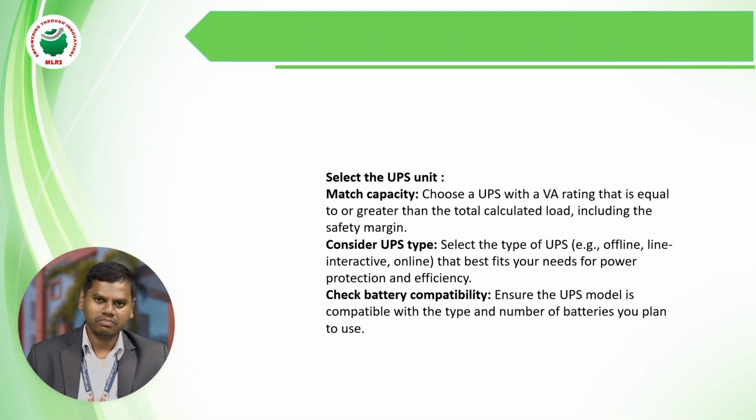So first, match capacity. Here, for matching the capacity of a UPS, we choose one UPS with a volt ampere rating that is equal to or greater than the total calculated load, including the safety margin. So this is match capacity of the UPS.